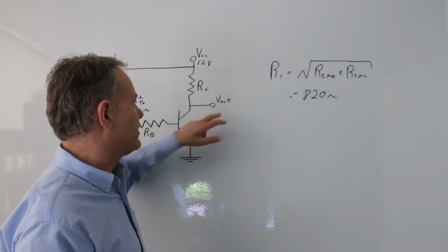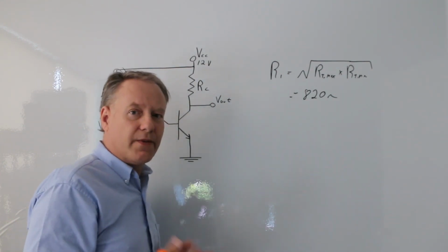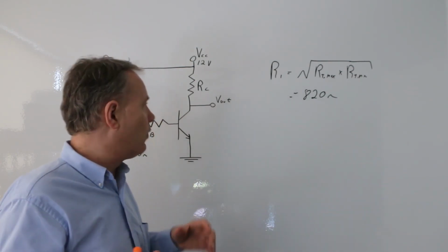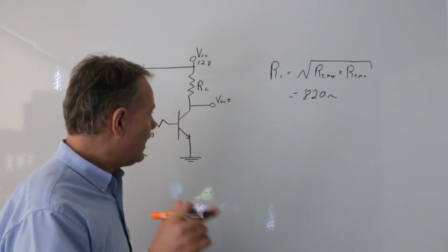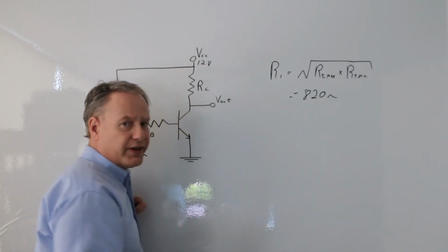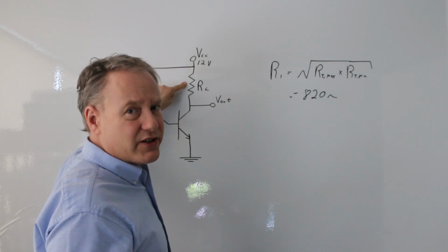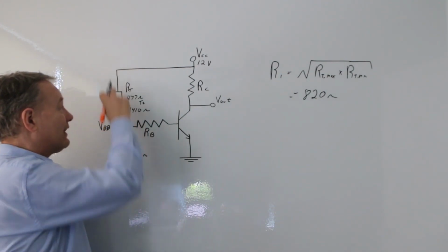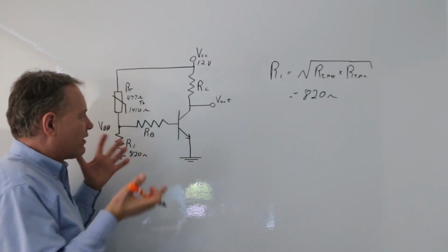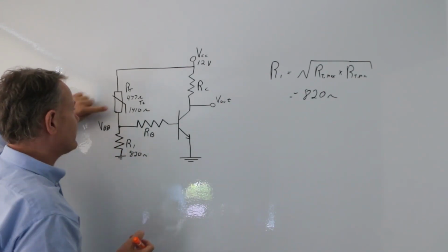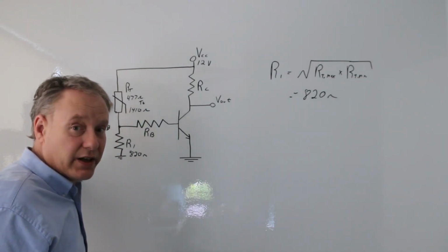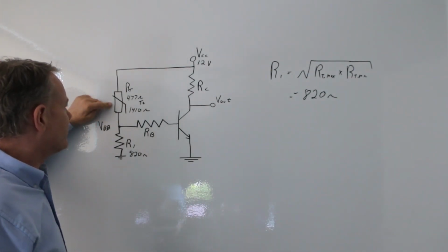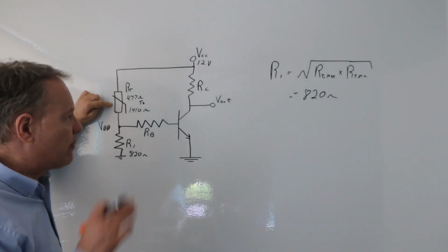So if I were to hook an Arduino up to this, if I were to have this going into a pin of an Arduino, the Arduino would be drawing like a milliamp, a really small amount of current. So that's actually important to know when we're choosing this. Essentially, I don't need much current to go through here. So the larger I make this, the better for me, because then I can make this larger, and if I make that larger, I need less current going through here, and it's all better if I use less current, especially through this thing, because that thing can only handle so much current. Later we are going to calculate how much current is going through here so that we can see whether this can actually handle this. But let's continue back on what I'm talking about over here.